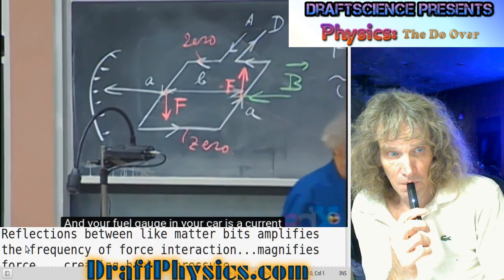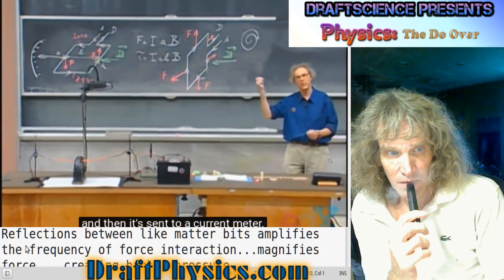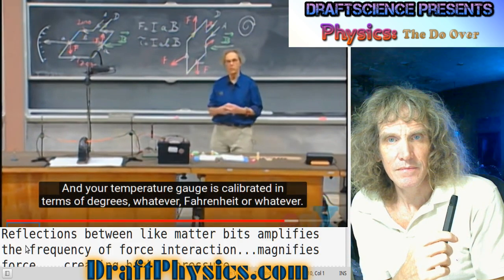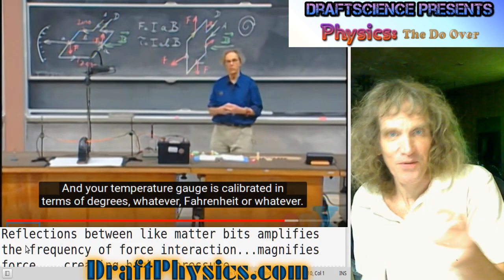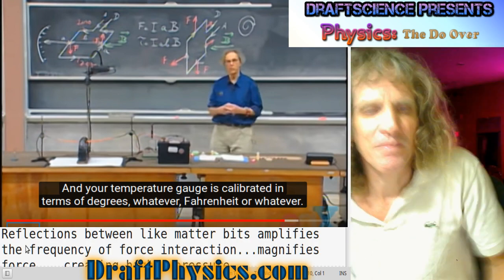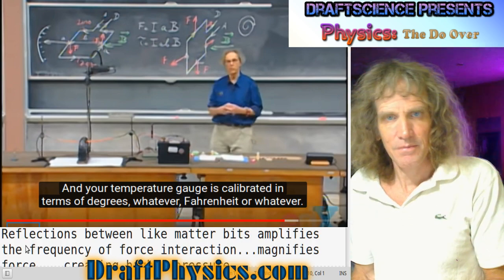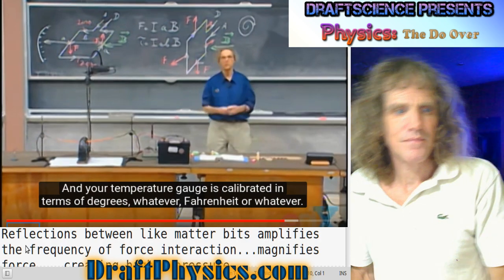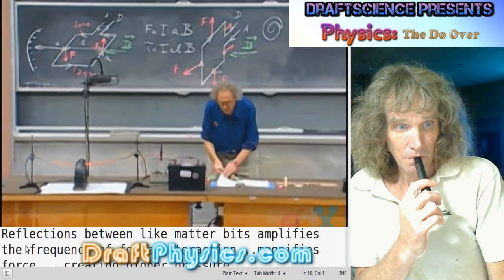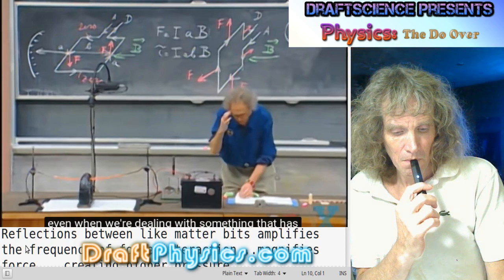That's the way that a current meter works. And your fuel gauge in your car is a current meter, except that the level of the fuel is somehow converted into an electric signal, and then it's sent through a current meter, and that's what you're reading. It is, of course, calibrated in terms of how much fuel you have. Well, the somehow in its simplest form is a cork floating in the gas, and as the cork moves up, it turns a magnet, and so on. And your temperature gauge is calibrated in terms of degrees, Fahrenheit or whatever. So these current meters are very common even when we're dealing with something that has nothing to do with current.